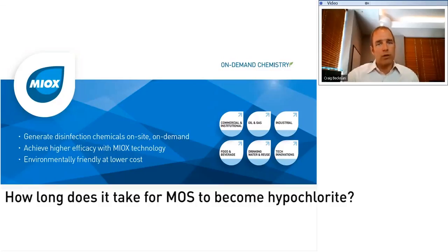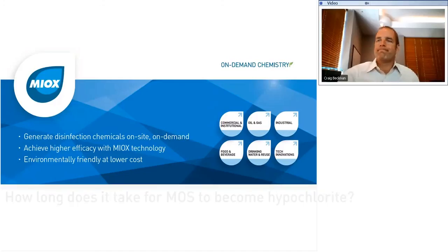You'll want to make sure that your brine tank and your electrolytic output tank, the oxidant tank, are sized such that you use that oxidant in less than a day. So if the usage at that 0.5% concentration is 600 gallons, put in a 1,000-gallon tank, not a 5,000-gallon tank, to make sure that you're using the mixed oxidant in still the mixed oxidant form.